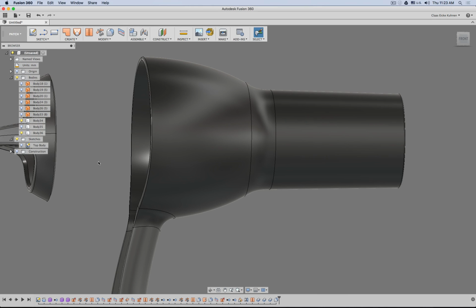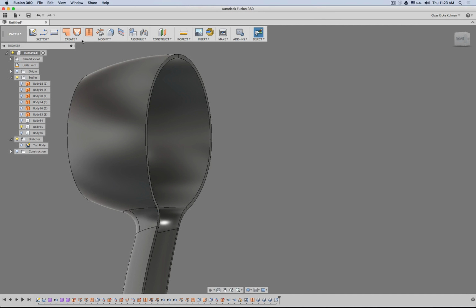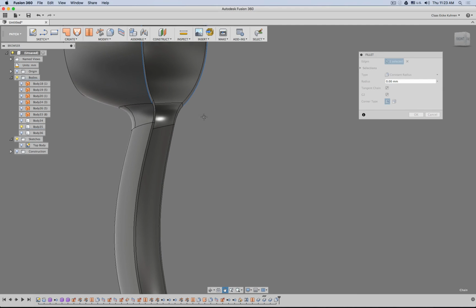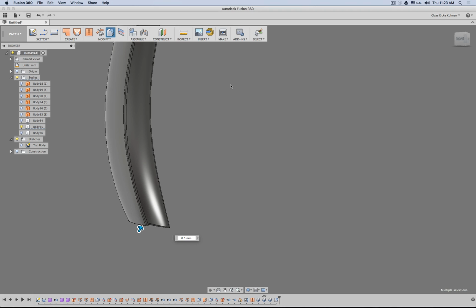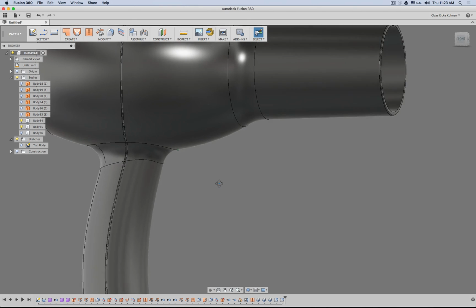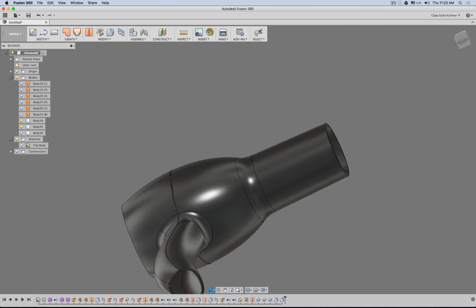So you see then when I bring this one in, let's hide this one there, fillet this edge, and this edge, this edge, this edge, and this edge, and maybe this edge, and 0.5. Okay, now I actually have even better render meshes because of the object detail level, look at that nice separation line. It comes across more refined, more believable.